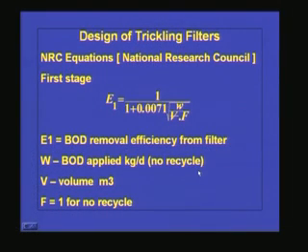So now we will see how to design a trickling filter. There is no theoretical approach available for the design of trickling filters. Mostly empirical equations are used for the design of trickling filters. That means in the field many biotrickling filters or pilot trickling filters will be available, and based upon their performance, the volume, flow rate, etc., and we know the influent BOD or COD and the effluent BOD, COD, based upon that the design criteria is developed.